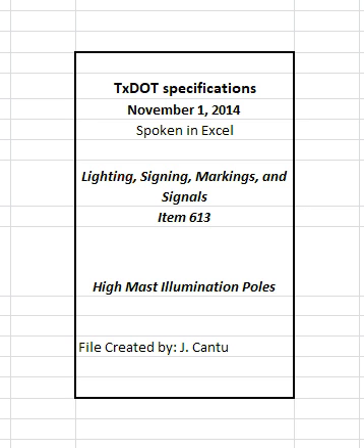Orient anchor bolts to provide 2 bolts on the reference line as shown on the plans. Ensure the anchor bolts are electrically bonded to the reinforcing steel as shown on the plans. Ensure anchor bolts and templates are rigidly held in position during concrete placement. Positioning devices may be tack welded to steel template, but not to any portion of the anchor bolts.